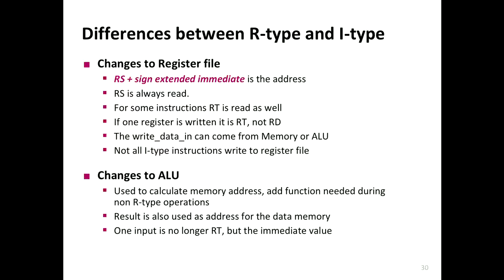Because remember, I told you that you can give a direct address also here, plus the immediate, the offset and the base address. So you can either have directly the actual data coming in from this memory location, or the actual value coming in from the ALU, because you're going to store from the output of the ALU.